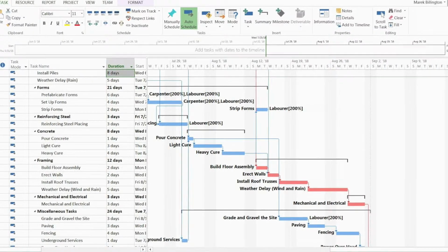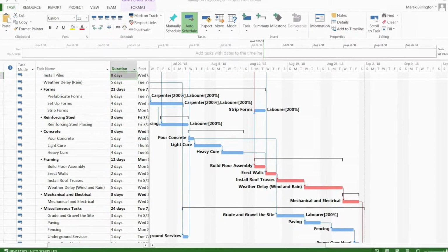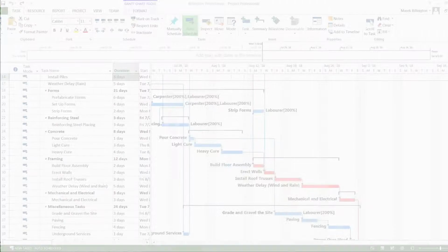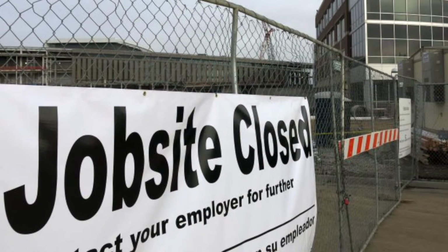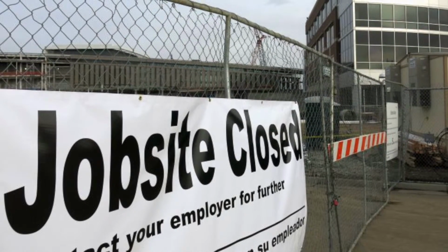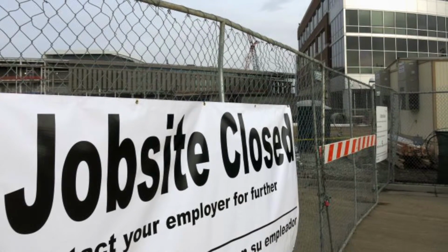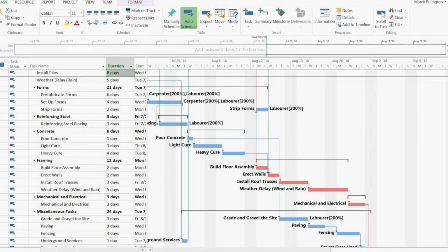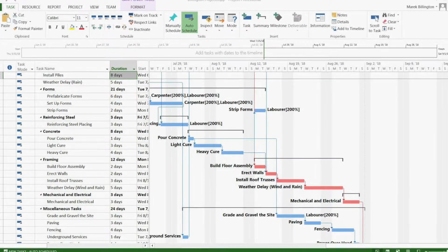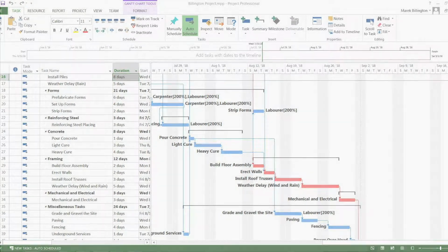The fix can cause a delay in the schedule by 1 to 3 days. Other trades cannot enter the building as the floors are being repaired. A small delay can cause a rearrangement of the booking of trades, creating more work for the construction manager and causing future scheduling conflicts with the trades that are expected to be working on the next job.